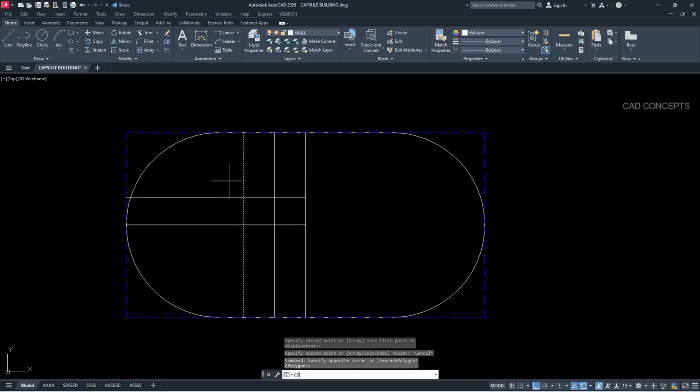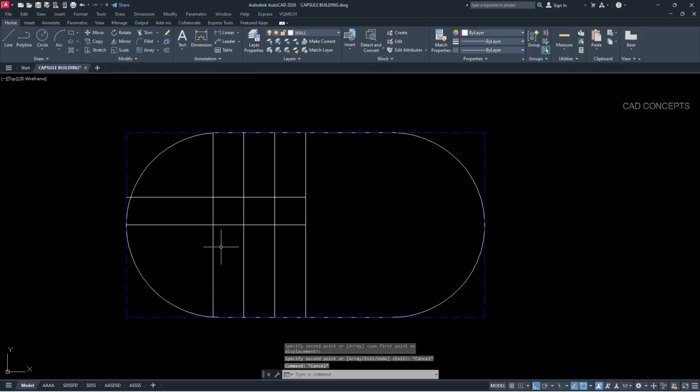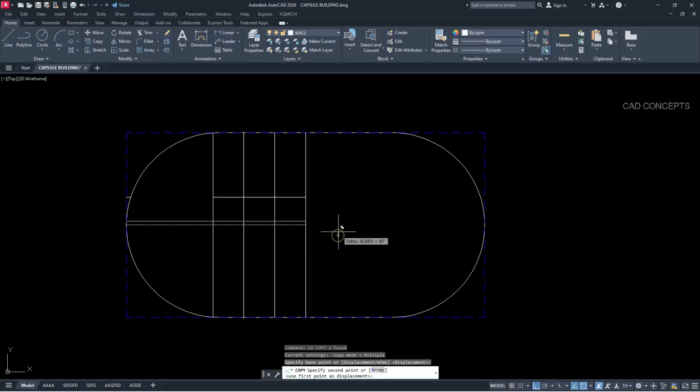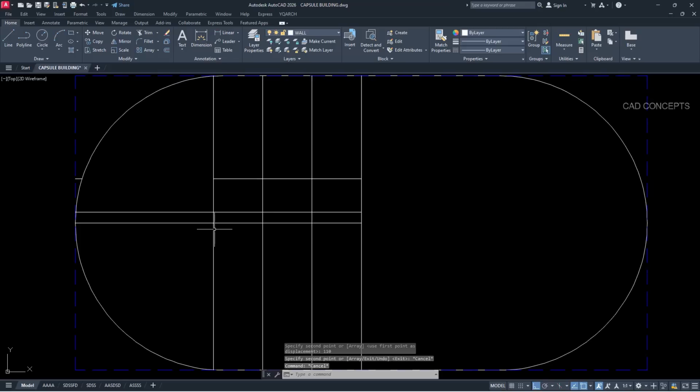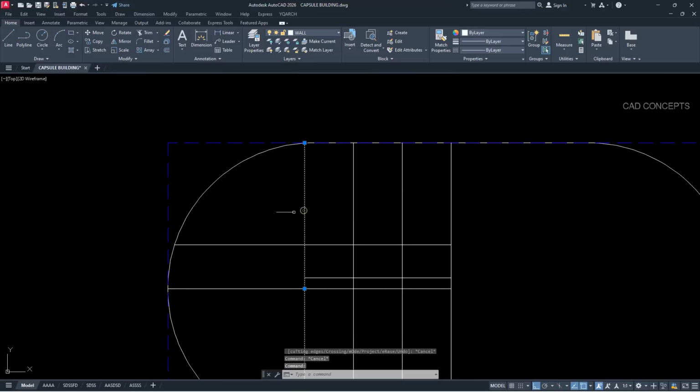And again the same. This is our living area and 2-bedroom, okay. So we will just arrange our center line, okay. After that we will do our design faster, okay. Let's do this here, 110 centimeter. So 110, 110, both sides will go 220, okay. We'll extend up to here and copy here.